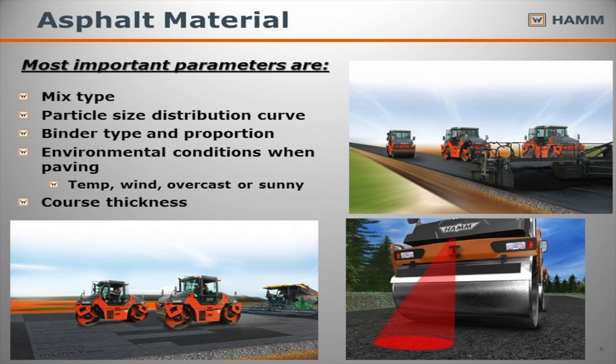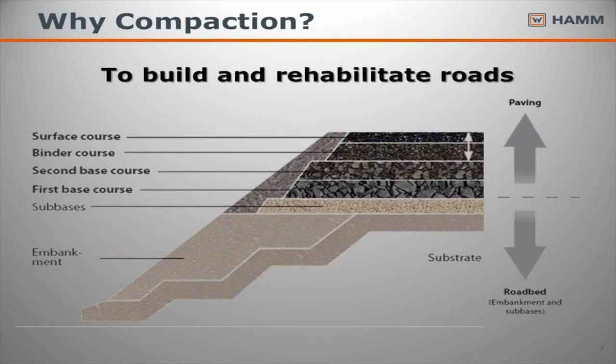The thinner it is, like Trenton said, the faster it's going to cool down. The faster it cools down, you lose your opportunity to get that compaction. It all starts from the bottom up. We can't not get compaction on the base. We have to get it from the bottom up. Bridging the material with hot mix is not going to do it, especially on the highways with the load capacities that we have today. It's not going to work.